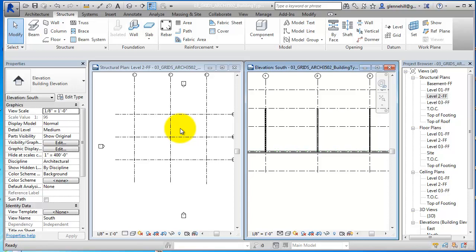There are ways to 3D copy, but once again, some elements actually can't be copied that way. Columns are one of those system elements that can't be copied 3-dimensionally. So you can copy them by moving a set of them in a vertical direction. And that's what we're going to do right here.